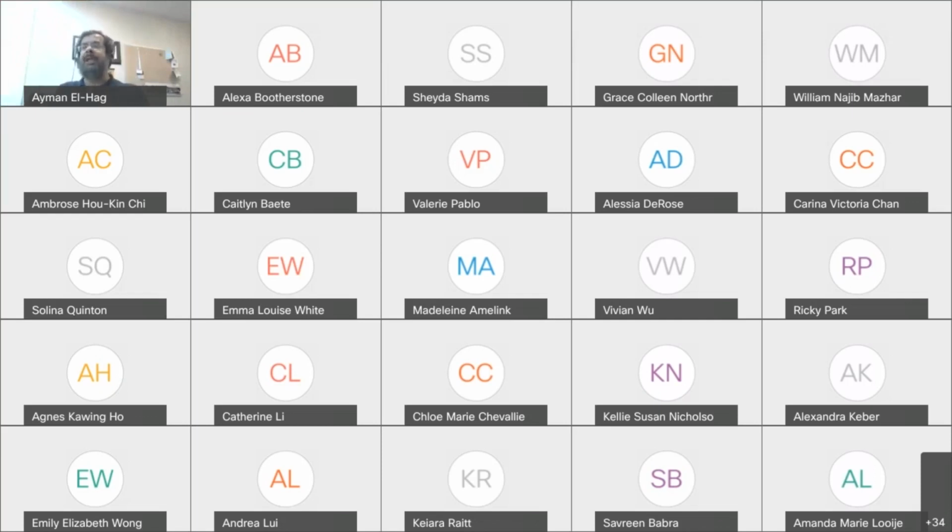What we'll be doing here, the difference between DC and AC, is exactly the difference between dealing with scalars and dealing with vectors. When we add scalars, we just add magnitude. When we add vectors, you have a magnitude and you have a direction. And you have to make sure that you add them properly. You cannot just add the magnitude of the scalars if they have different angles. So that's basically what we will be tackling on Thursday.